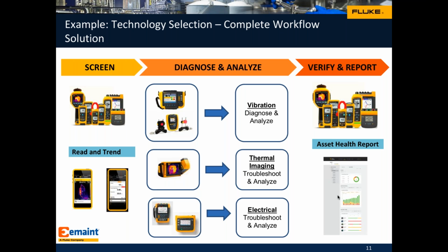A few of our customers who have distribution centers across the U.S. often start dabbling a little bit with PM. They may have a small PM, but it's really not regular. What a few of them do is hire a third-party company to do thermal imaging. They say, hey, we have about 300 or 400 assets, can you please take a picture of all the assets on a regular basis? And they do this once a year. Once that third-party company completes the verification, they provide a report with recommendations: you have these 59 assets that need to be looked at.